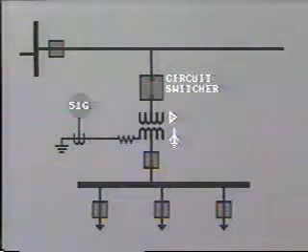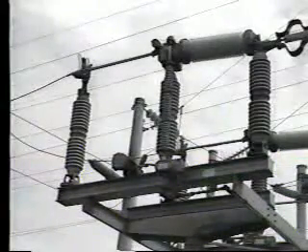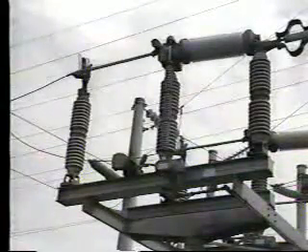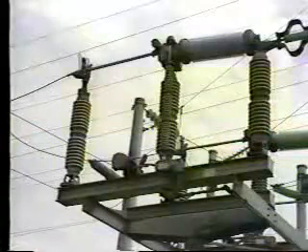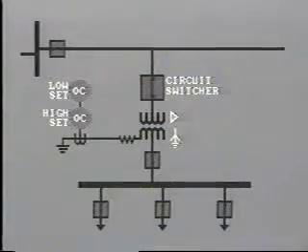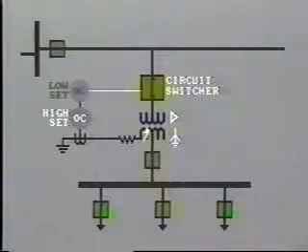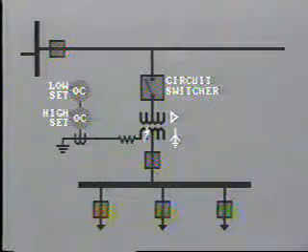Generally speaking, the ground switch arrangement is not often used on new installations. Instead, a circuit switcher may be installed on the transformer primary instead of a high-voltage fuse. This is far less expensive than a circuit breaker, but in return it provides very limited fault interrupting capability. If the fault current is low, this switcher will be quite capable of interrupting the circuit.